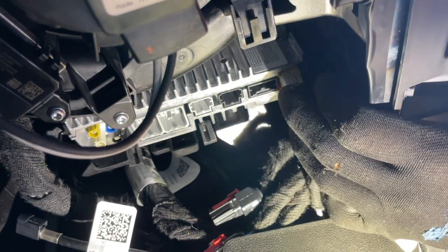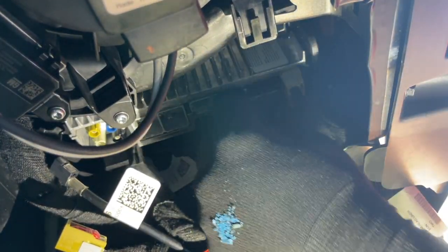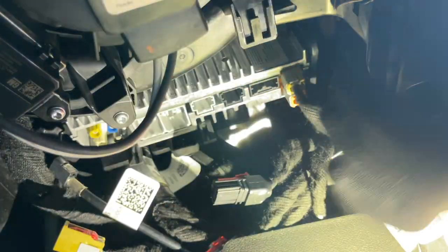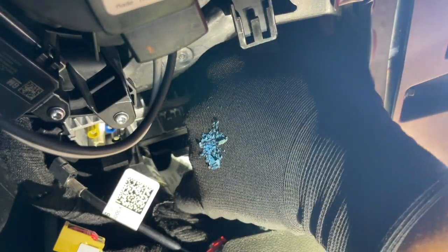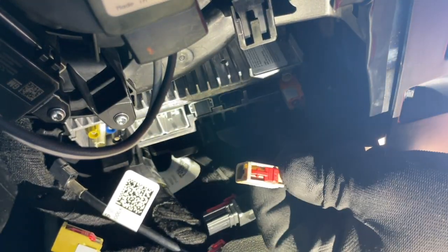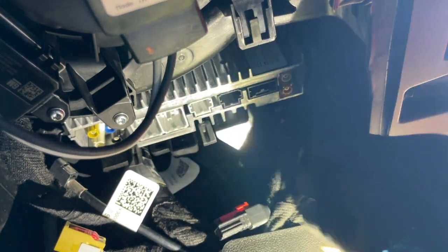And finally, the last 2 connectors here on the right are going to be similar to these cables here. Pull the red CPA down, and you want to press in. These cables on the right, the red TPA is actually to the right. So you want to get your hand underneath here, slide the red CPA down. And again, this is where the sharp edges are right here. So just make sure you have some tape on that sharp edge or you're wearing gloves. CPA down, and then you unplug. There's 2 of them. CPA down, squeeze, and then unplug.